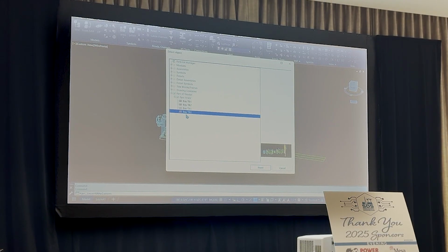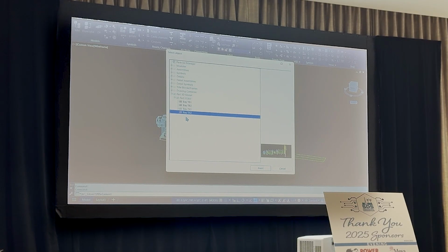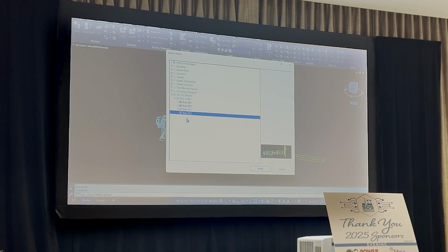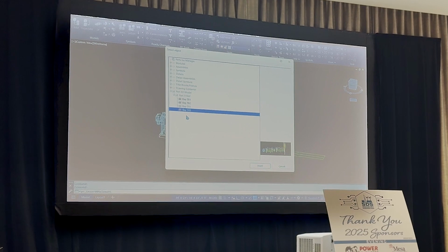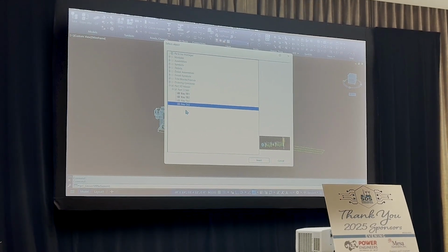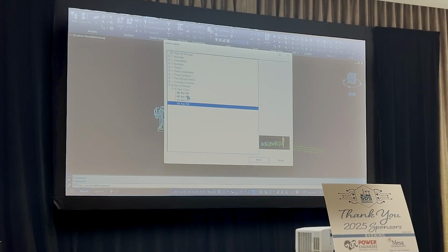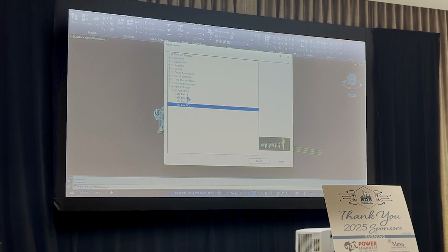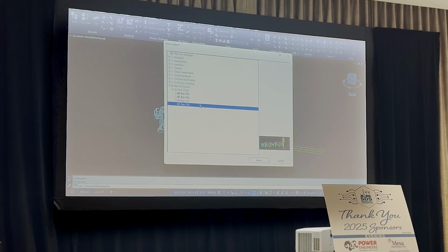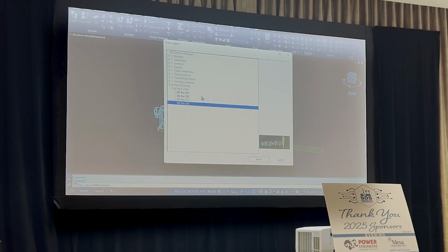If you had a collection of these that you did want to reuse, you could do it as a module and then just drop it into the bay. So you're still making bays, but you're just dropping one module into the bay for this. If you change a module, it changes everywhere across the station. So if I went and changed that breaker switch, it'll update everywhere that I use that module. Whereas with bays, if I had to make a change to just that TX1, I can make a change to just it without affecting that one that I copied or any other, right? So if you have things that you know are going to change, and whenever they do change, they consistently change across the whole station, you can make those modules.